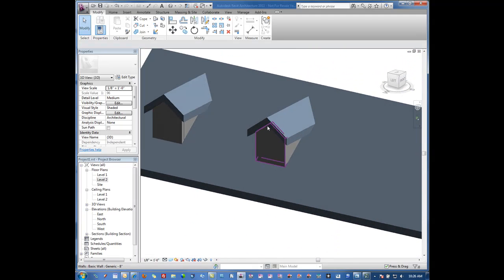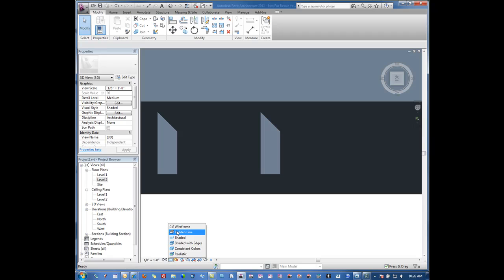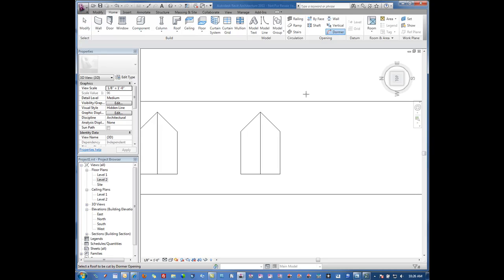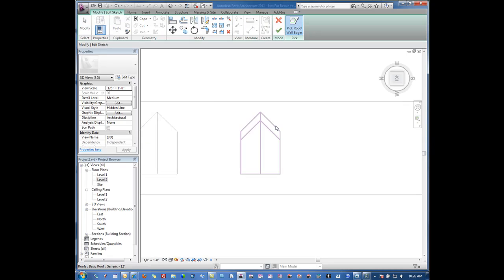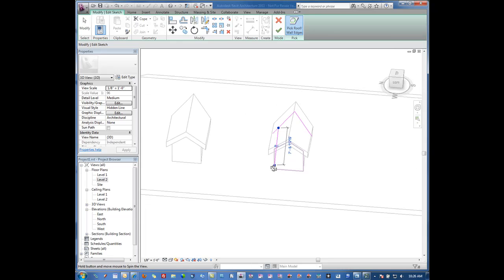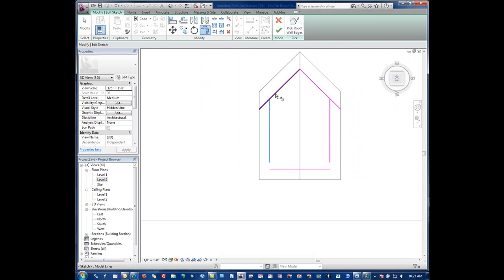The next thing we need to do is cut a hole through the roof. So usually I'll do this in a plan view. We'll go over to the Home tab, and we'll say Dormer. We'll select the main roof that we're cutting, and then we'll select pick roof edges, and we're going to select the roof. And then also we're going to select the walls. So we'll select this wall, select this wall, and the front wall. Final thing we'll do is trim those up. And then finish.